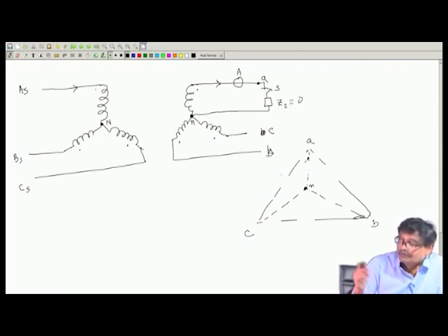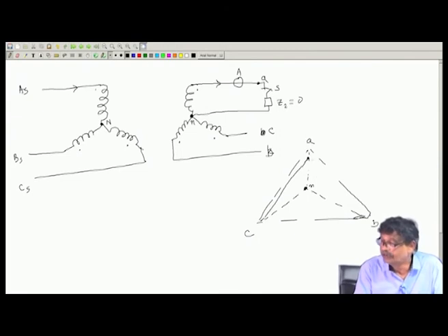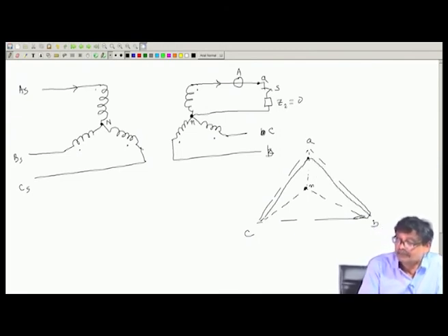So, when you try to load the secondary of a transformer by a single phase loading, this neutral point has come over here, indicating that the voltage applied to the other transformer is B n, which is almost line to line voltage B A, because this is shorted.